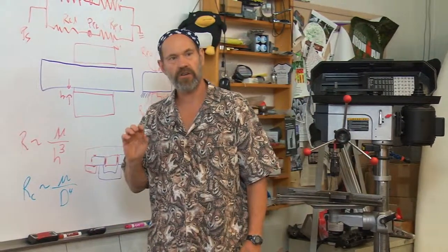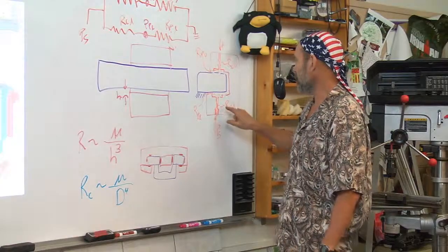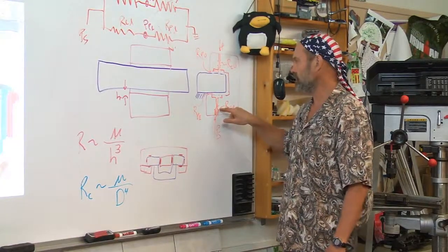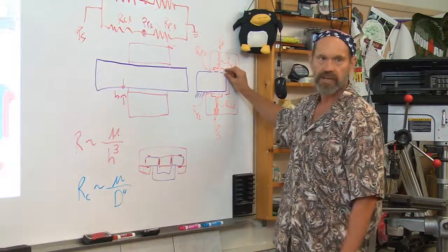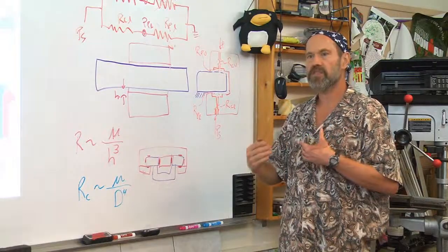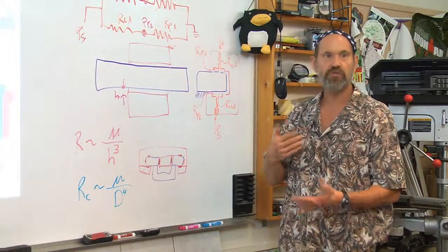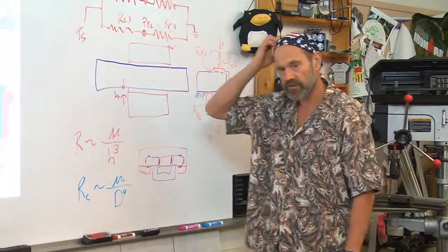So there are designs that are called self-compensating designs, where the structure of this compensation unit actually gets its resistance from the bearing gap on the opposite side. And there's a number of different ways of doing this. They all rely on the principle of self-help to allow them to self-tune to give you the optimal compensation resistance. So you can read about those.